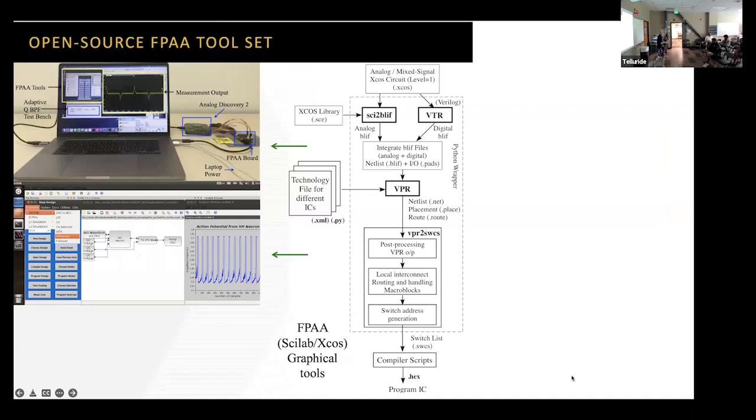But it's the correct prototype. I think that's the question. I can learn more in 5 minutes of playing with a real physical circuit than in days of playing with SPICE. Those of us who fought SPICE, trying to get the parameters in a reasonable way for a reasonably accurate simulation, still can't really trust that. SPICE will always converge? Not always. I do have counterexamples. A system like this has a lot more parasitics. Although sometimes you can use those parasitics too.